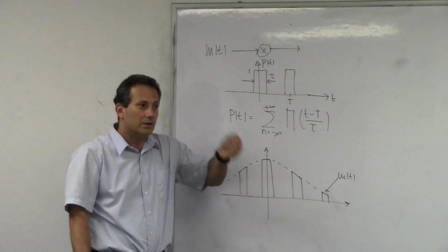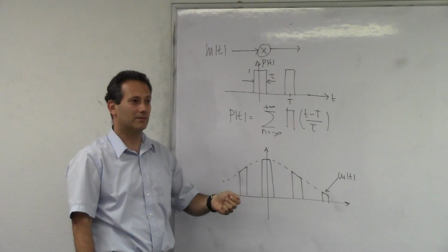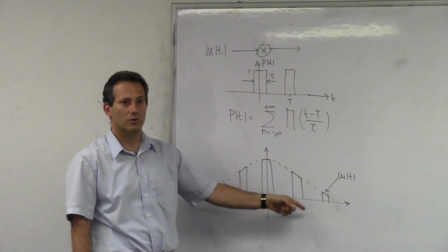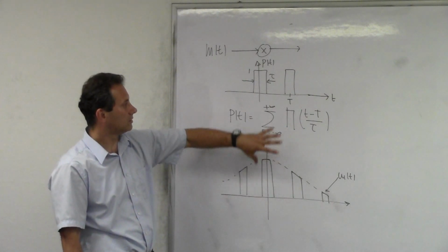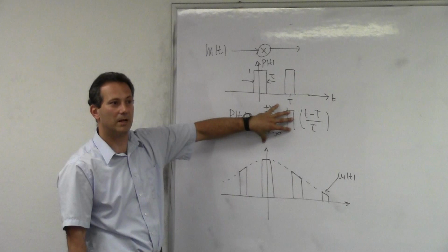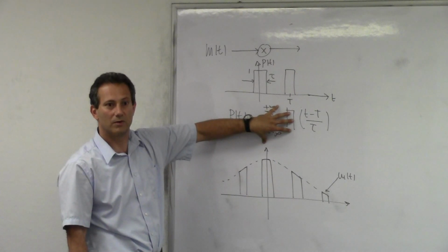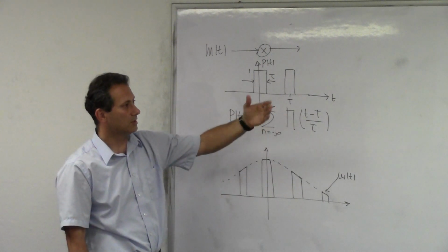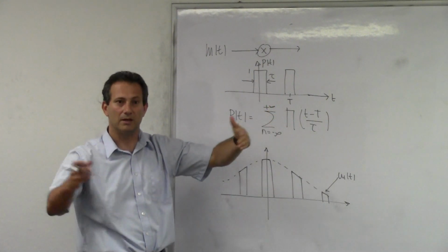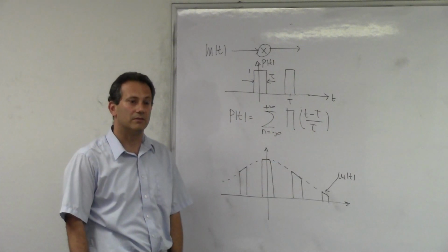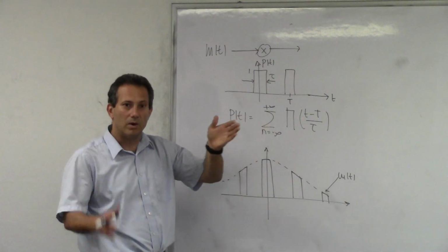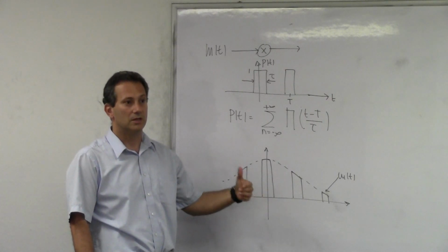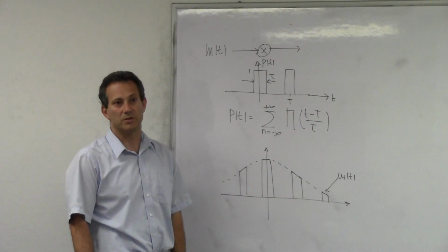You just flip the switch fast enough, and then you let the signal go through, don't let it go through. So this is equivalent to taking the original signal and multiplying it with this train of pulses, not impulses, pulses here. And that periodically extends the signal in the frequency domain, and then you pick the one centered around the integer multiple of the fundamental frequency that you want to use for the transmission.